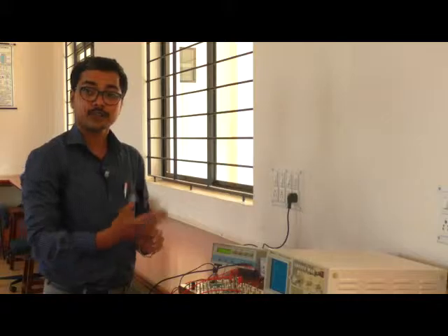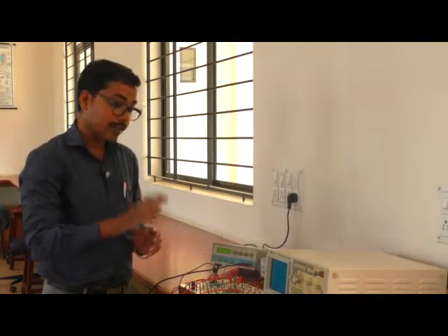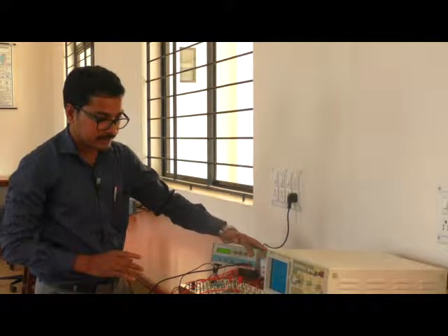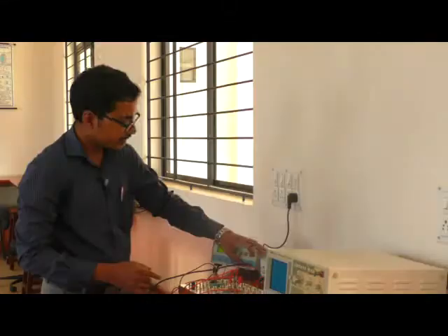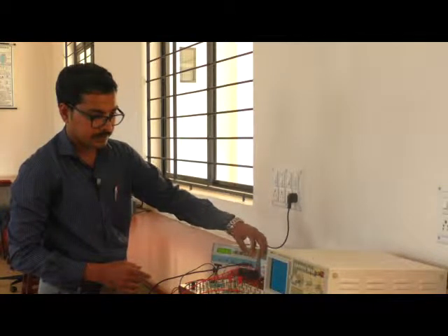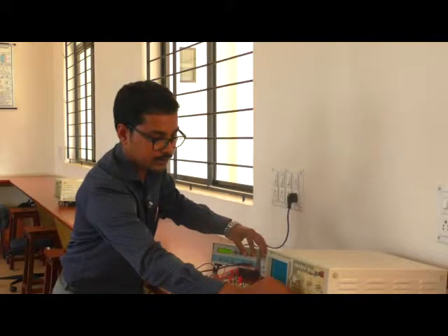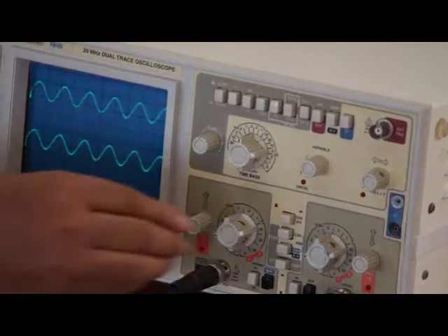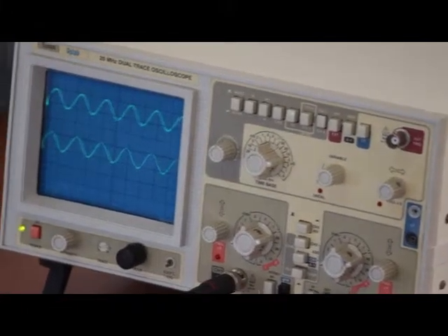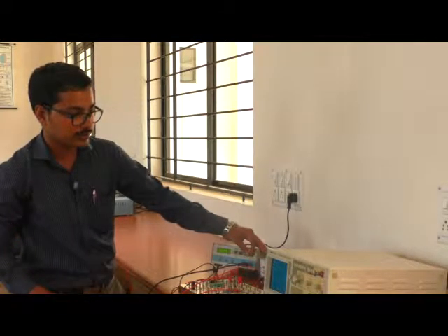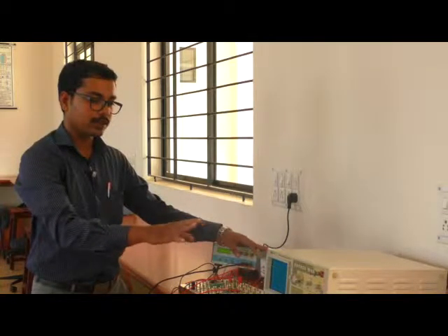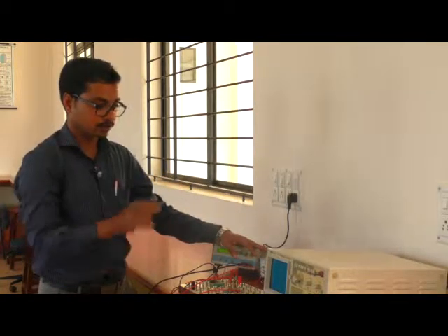Now we have to check for different values and different waveforms so that we can conclude that it is a voltage follower circuit. For that I am increasing the signal strength. See that the corresponding signal strength is increased. I will reduce the voltage division so that we can go for different values. Now the division is 5 volts and the signal covers almost 1 division, so it is 5 volts. Here also we are getting the corresponding voltage. Increasing further, it is now 2.1 divisions into 5, which is about 11 volts, and so on. For any value of the applied input voltage, the output is following the input.